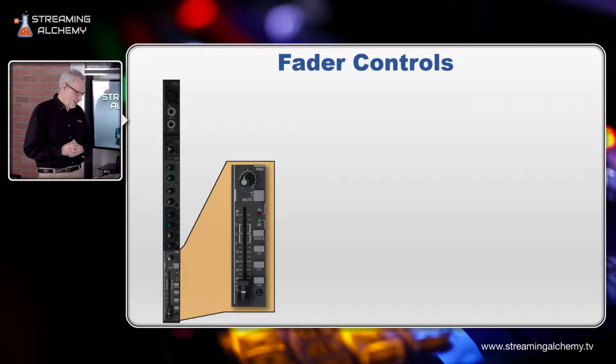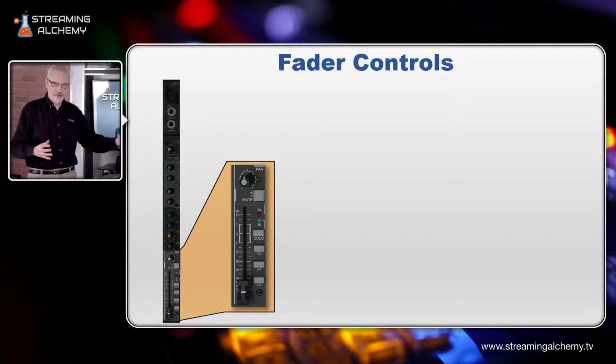Okay, so we've gone through all of the processing steps that are involved in bringing audio into a channel on a mixer. So the last step here is really the routing. Now that this sound has come in, where do I want it to go and what levels do I want to send it out at? So let me start at the top.